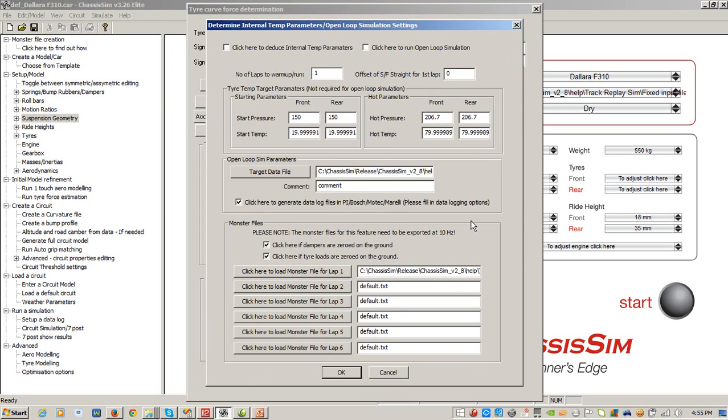For the uninitiated, the monster file is an ASCII tab delimited file that contains track distance, RPM, lateral G, longitudinal G, your forward damper displacements, and steered angle at the tire. That's basically your input steer, but measured at the tire as opposed to the steering wheel. It also contains throttle and speed. Once you've got those, you can pretty much run the track replay simulation. With the adjustments we've made, it effectively uses the speed and the steer inputs as a target to go.